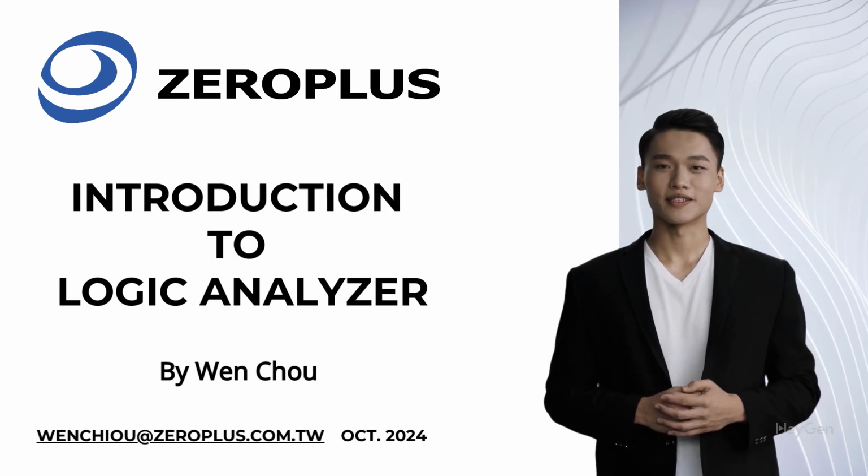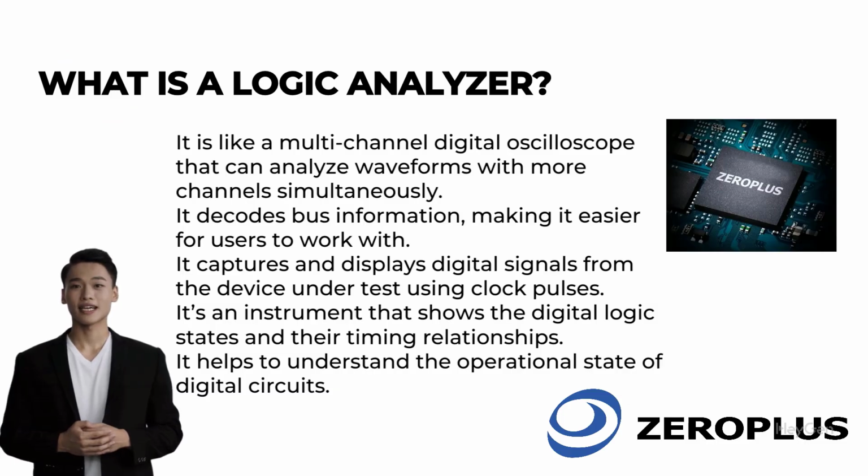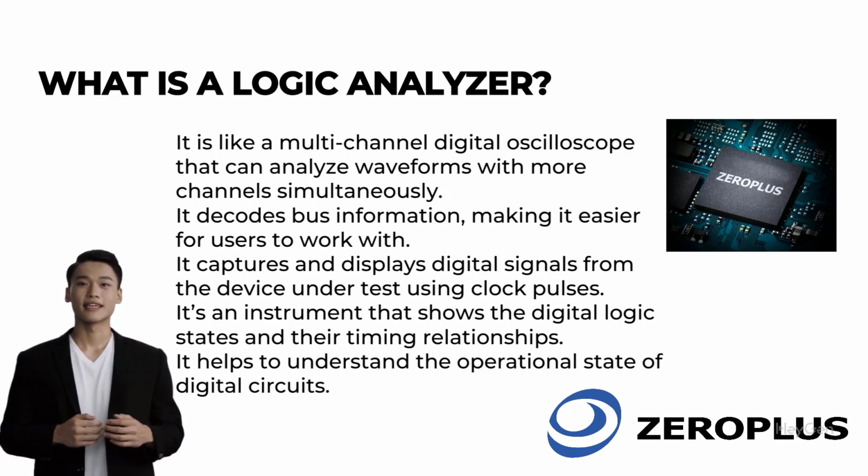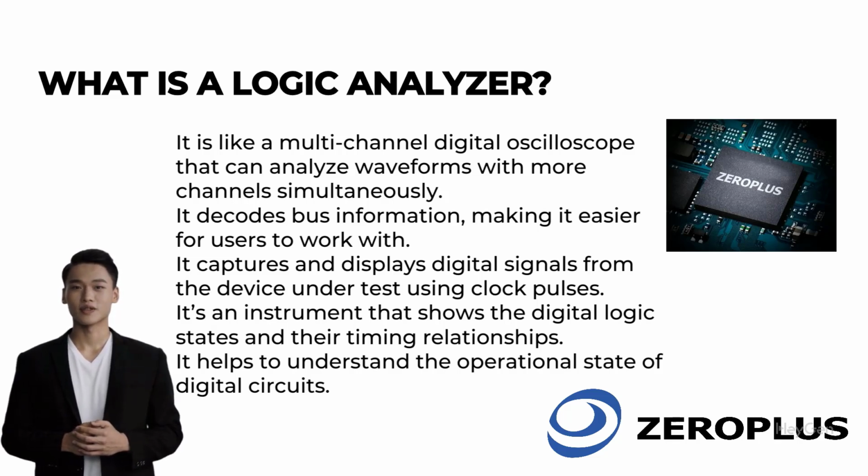Introduction to Logic Analyzer. What is a logic analyzer? It is like a multi-channel digital oscilloscope that can analyze waveforms with more channels simultaneously. It decodes bus information, making it easier for users to work with. It captures and displays digital signals from the device under test using clock pulses. It's an instrument that shows the digital logic states and their timing relationships. It helps to understand the operational state of digital circuits.